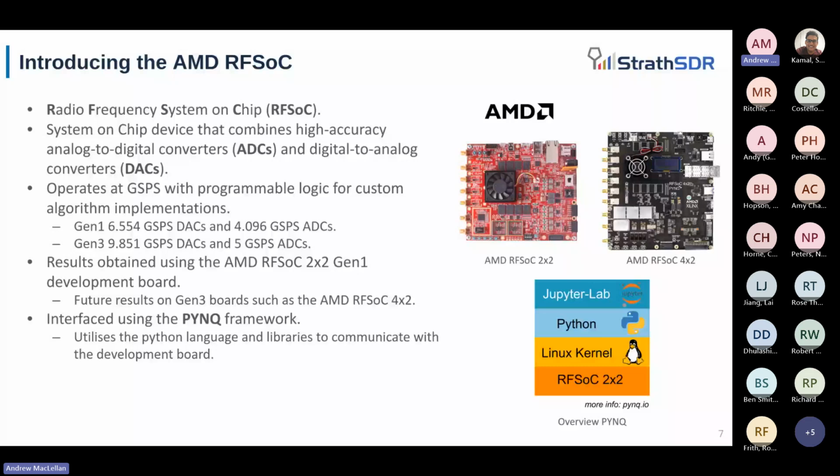The results that I've done for this, the stuff I'm talking about in this presentation, I've done with the RFSoC 2x2, which is a Gen 1 device, but I'm hoping to move on to a Gen 3 device and a more recent device, such as the RFSoC 4x2. We're interfacing with these boards using a framework called PYNQ, which utilizes the Python language and libraries to communicate with the bitstream on the development board.